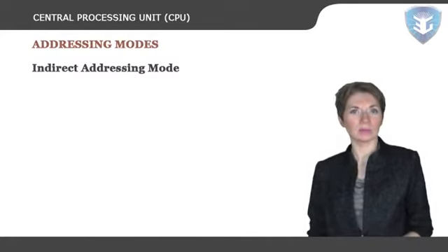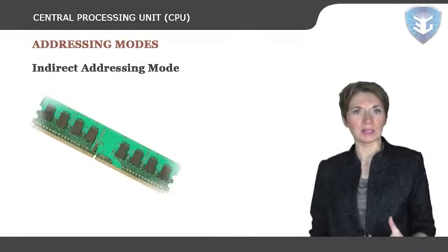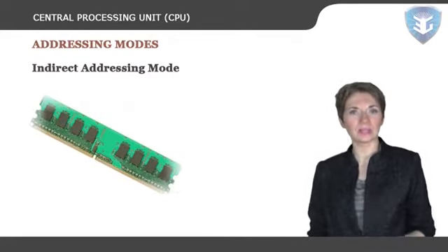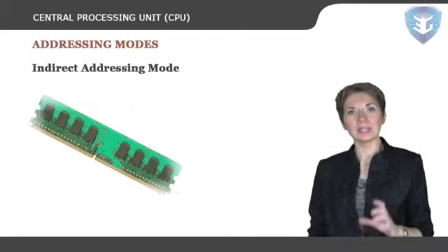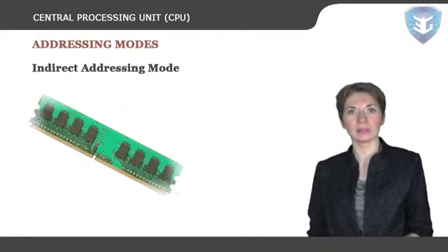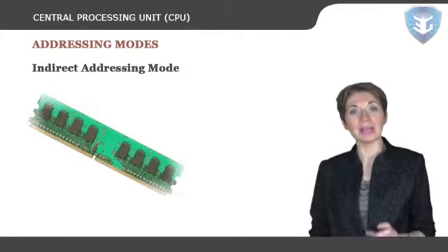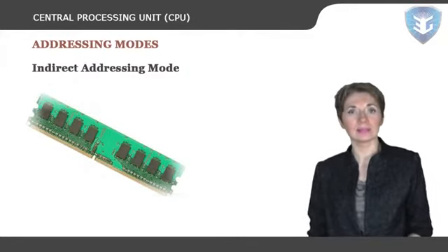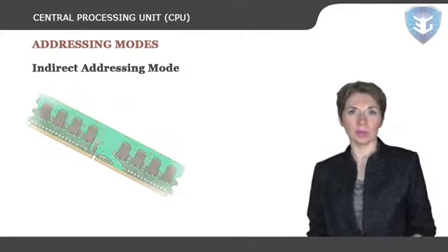Indirect addressing modes. In the indirect addressing mode, the instruction specifies a register which contains the address of the operand. Both internal RAM and external RAM can be accessed via indirect addressing mode.